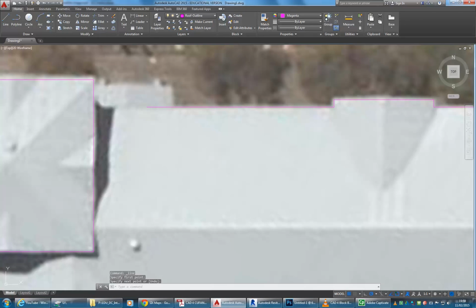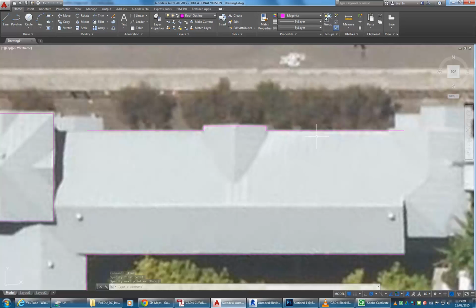But this one is obviously quite a bit off 45 degrees, and you can tell also because the ridge line there is not even. So if you ever see a line where two roofs connect and they're not 45, then you know that there's a roof that doesn't have an even pitch, which is unusual. You can work it out, but there's a bit of maths involved. Here, the easier way would be to go and count bricks to the ridge. Yeah, that roof there is at less of a slope than this roof here.